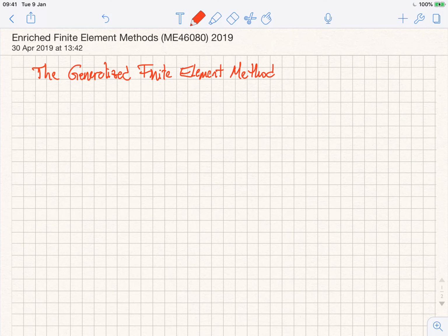And they could use the Generalized Finite Element Method to basically model fracture mechanics problems. These people called the method the Extended Finite Element Method, right? So basically, it is an application of GFEM to solve problems with discontinuities. This is what people today know as the Extended Finite Element Method, or XFEM. But they are indeed the same method, okay? GFEM, you could argue that it's a broader family of methods, because you don't have to only choose enrichment functions for discontinuities, but you can pretty much use anything you want, right? As we discussed.